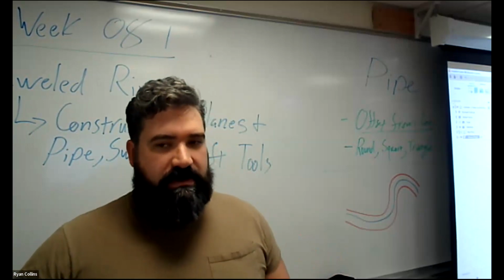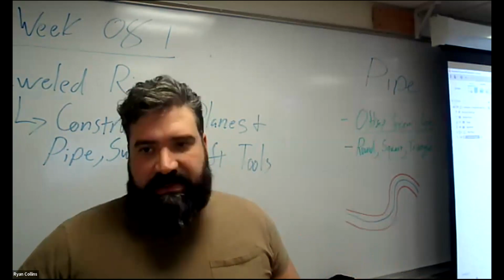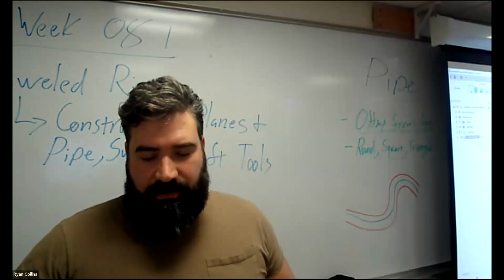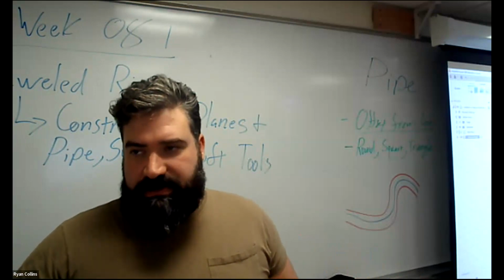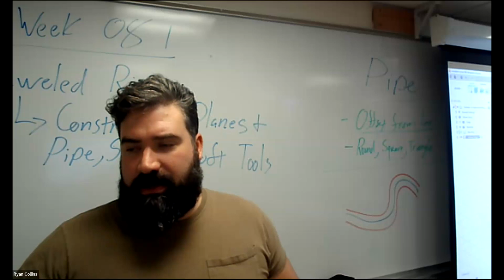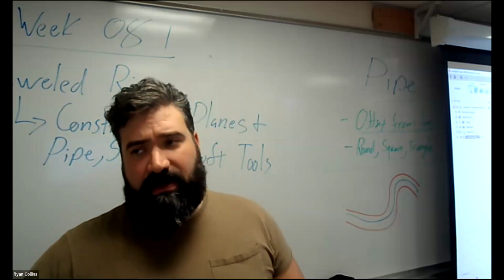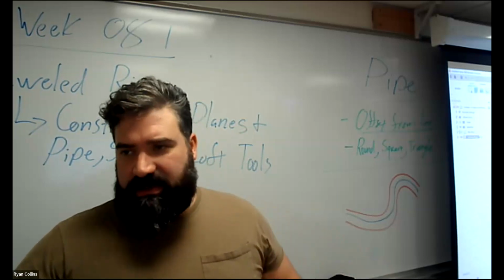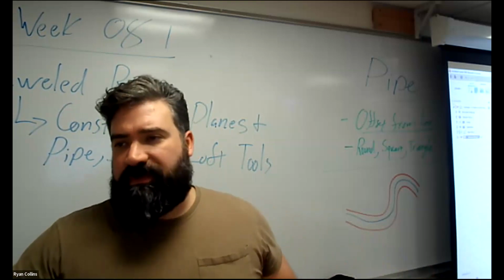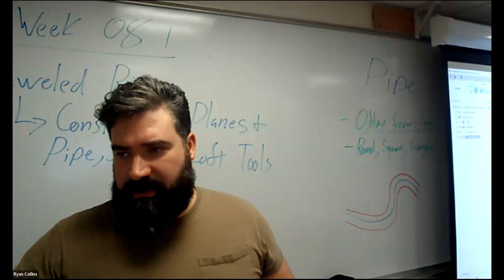Now, yes, it's a circle. So what I would need to do in this case is, I can create a point, or I can just create a profile on that circle. That's fine. There is construction on construction planes. You can do a plane at an angle. Usually, just what we've been working with, offset plane, which is just taking a predetermined plane off of your origin points. You know, the XY, XZ, YZ, that sort, and moving forward off of that. You can do tangent planes, midpoints, all that sort of thing. We're going to talk about these here in a few.